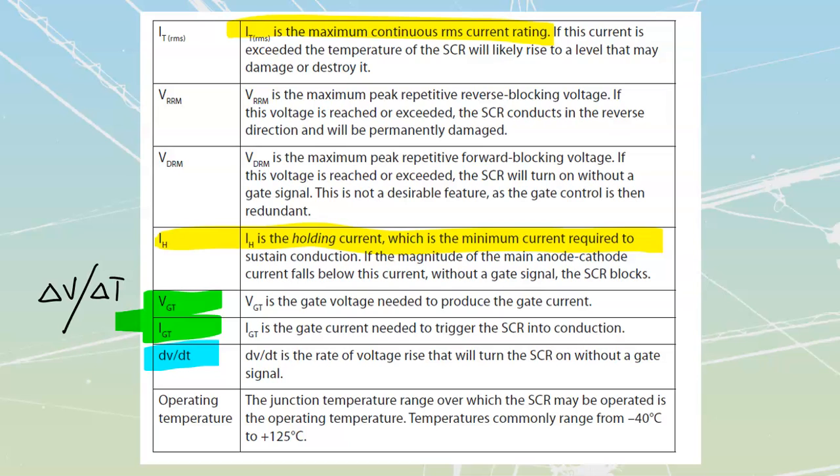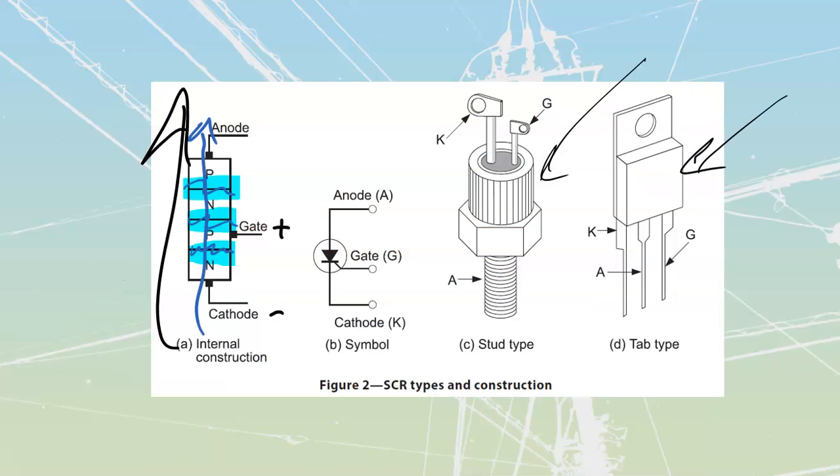over a short amount of time, we can basically just shock some of our devices into conduction. Because we go to a super high value of voltage over here and, in the opposite direction, a negative value of voltage in this one here, we all of a sudden flood this section over here with holes, or with electrons. We flood this top section with holes, and it can be enough that it just cascades over into here. This one can cascade over into here. And if these ones flooded fast enough to cascade, the two of them together will be able to overcome this one, and all of a sudden the whole thing just goes right into conduction.